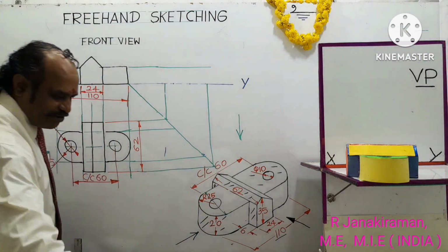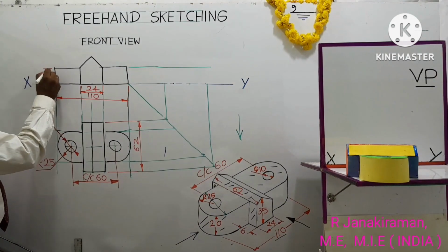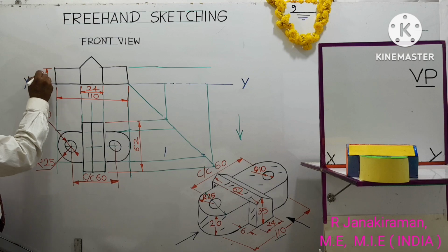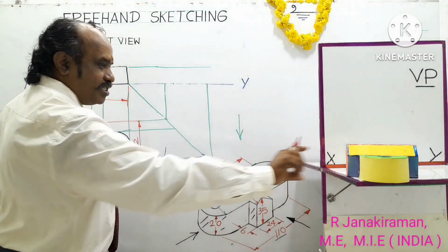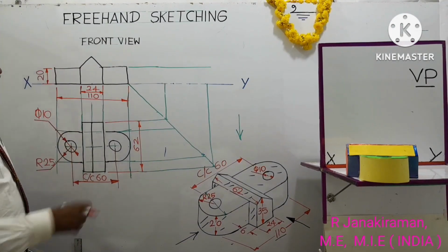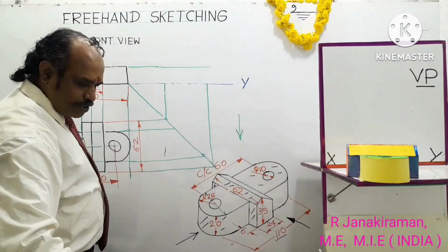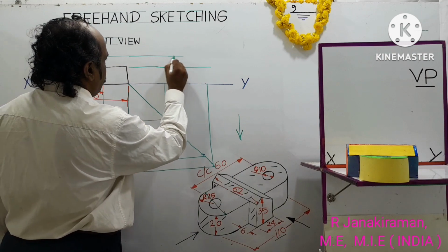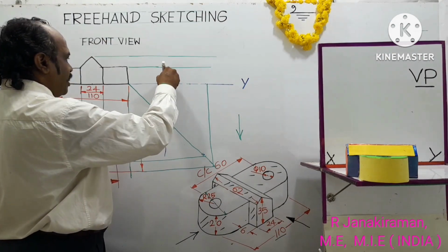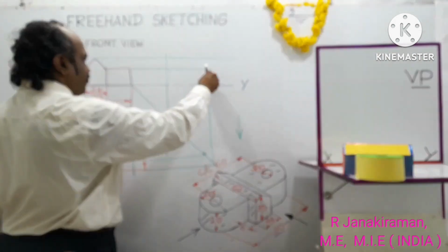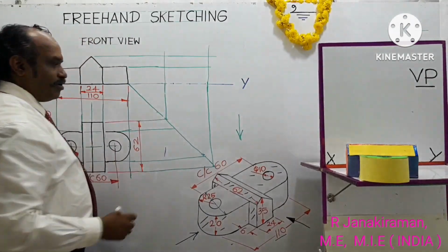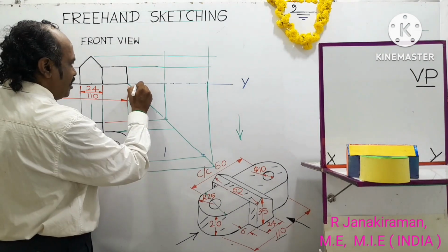Let us dimension it in the front view itself. Put an arrow and shade it. The breadth of the yellow portion, that is the height of the portion, is 20 mm, which we did not do in the front view. Okay, so this peak point is also traced using a 2H pencil, called a horizontal projector. So you will get a rectangle. This forms a boundary for the left side view. So the horizontal line is also extended.